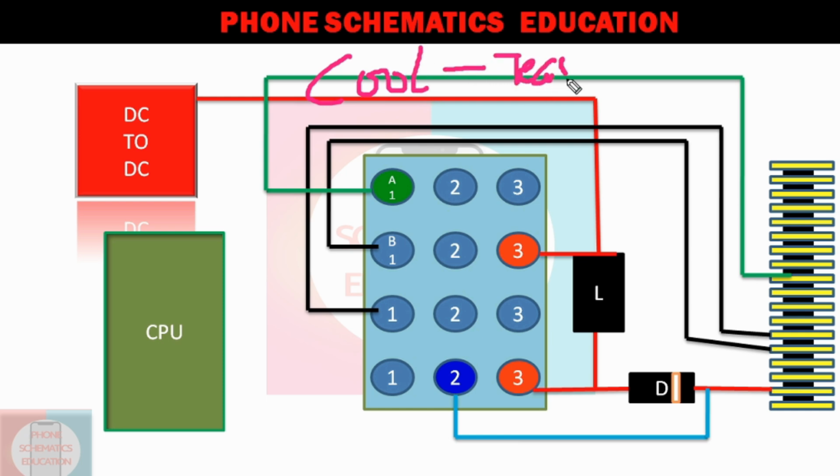In this type of testing, we test with the multimeter on diode mode, with no connected power source, I mean no charger or battery. Testing only on the motherboard, with the multimeter on diode mode, preferably in reverse bias. Now, what is reverse bias? I already told you in previous videos. The other testing method is hot testing. After the cold testing, we can check hot testing.